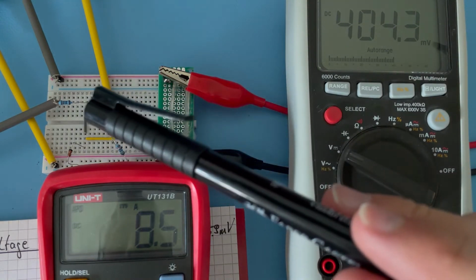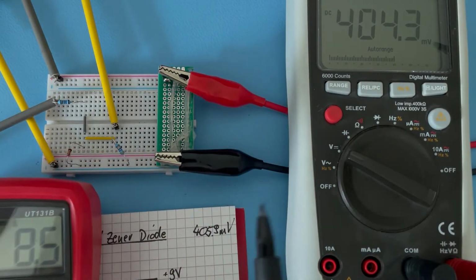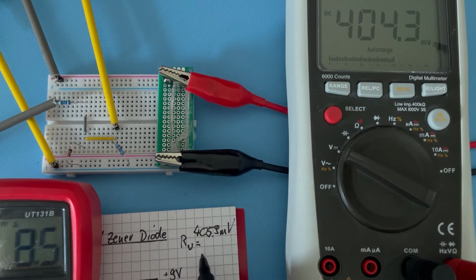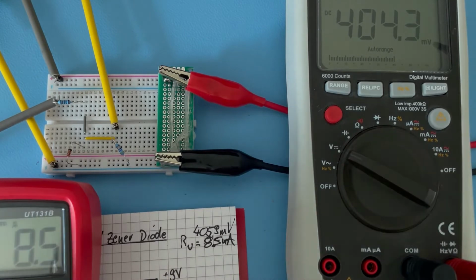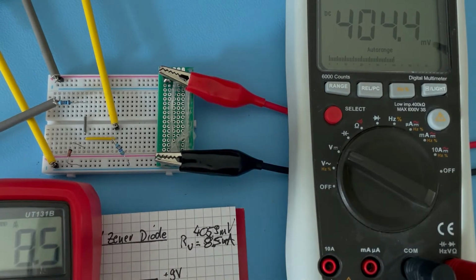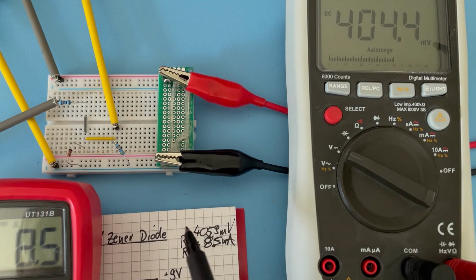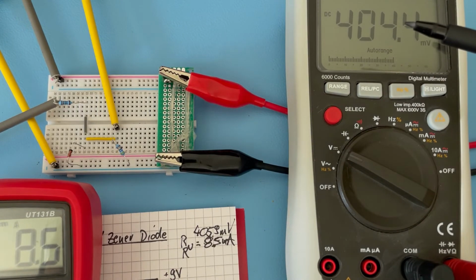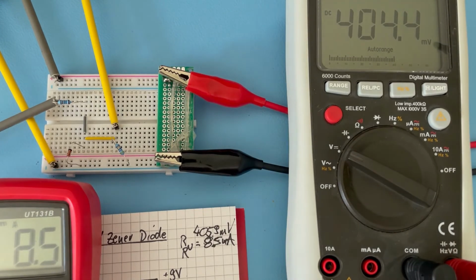to the upper resistor here. So I note that down. Resistor U, I abbreviated for upper resistor: 8.5 milliampere. And then I would be interested what flows through the lower resistor, but we can tell because of the millivolts across the resistor. We can tell what flows through the resistor, and then we can logically derive what must flow through the Zener then. Okay, that's the setup.